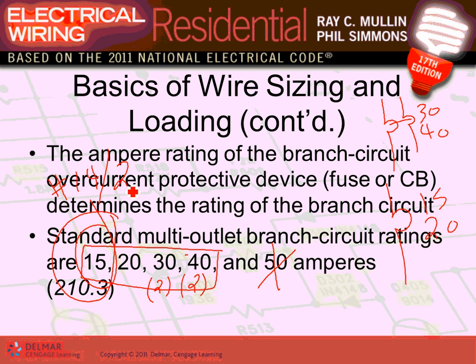So please write yourself a note, please, before we go. So this one is also with 12-2. This one goes with 10, typically 10-2. This one will go with number 8, 4 conductors. 8-4, or 8-3, so we need 2 hots and a neutral. 8-3. Sorry. Oops. Now I can't delete that one. 8-3. Why 8-3? 2 hots and a neutral, and the ground we don't count it.